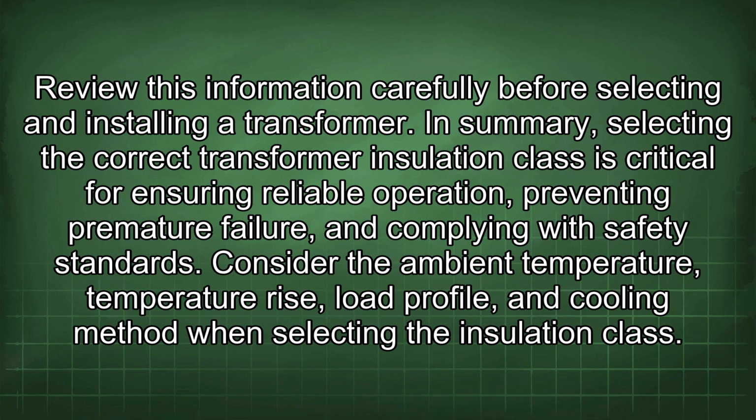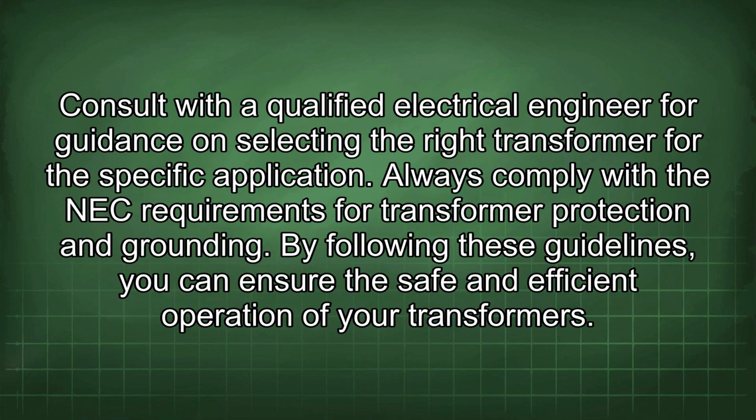In summary, selecting the correct transformer installation class is critical for ensuring reliable operation, preventing premature failure, and complying with safety standards. Consider the ambient temperature, temperature rise, load profile, and cooling method when selecting the installation class. Consult with a qualified electrical engineer for guidance on selecting the right transformer for the specific application. Always comply with the NEC requirements for transformer protection and grounding. By following these guidelines, you can ensure the safe and efficient operation of your transformers.